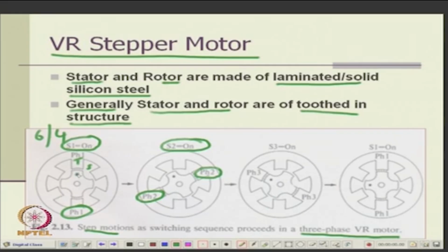You see this dot has moved here. So, the movement is in this anti-clockwise direction. It has moved up to this step angle, and this step angle will be the difference between the axis angles. I think you can easily find out what the angle is. Now, after phase 2 you put phase 3 here. If you excite this, switch 3 is on, then what will happen? This will come like this, is it not? So, this dot, this point has come here.